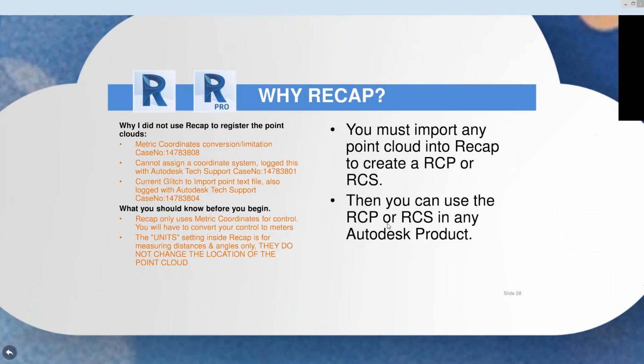I always like to talk about too, and maybe if Autodesk is down here, they should probably cover their ears for a minute, but there are some limitations with Recap. So one of the things I really don't like is the fact that it's in meters. So everything's in meters. Even if you have ground control or coordinate system, it has to be converted to meters in order for you to specify that when you're doing registration. I've also had some issues with sometimes the coordinate system just doesn't work for me, and there's just some glitches with those.